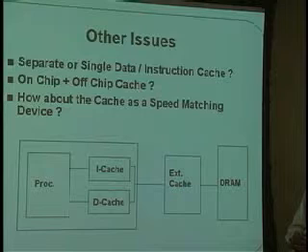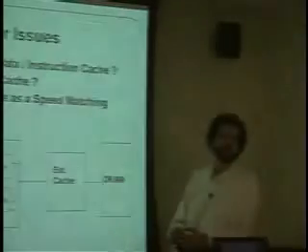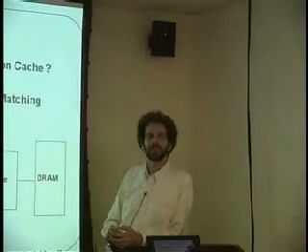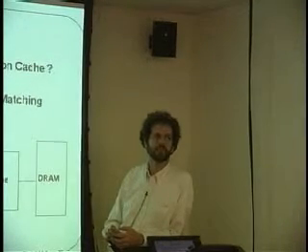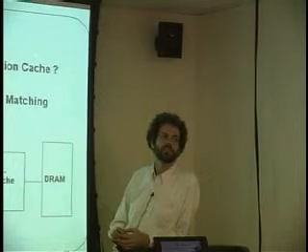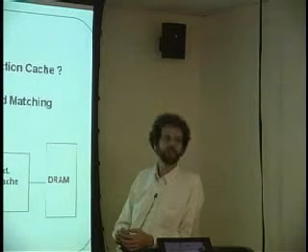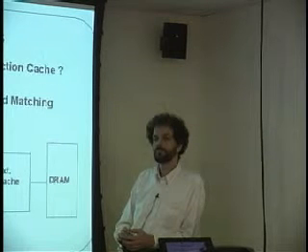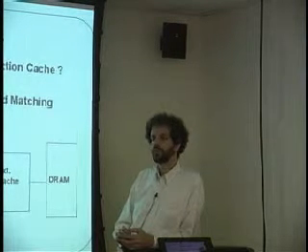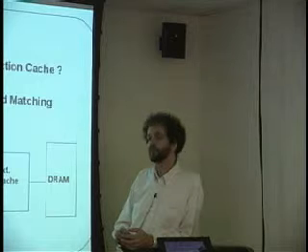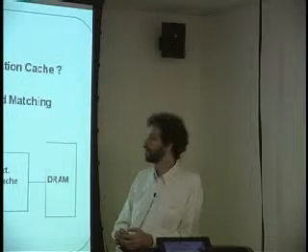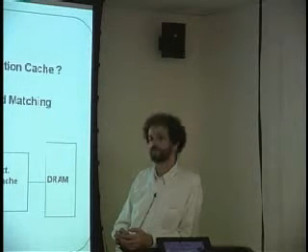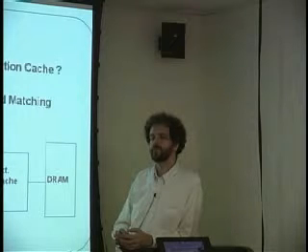And the reason is, again, the machine has a voracious appetite. And it's executing opcodes like crazy, okay? What it's not doing is executing loads and stores on every opcode. And so you typically see that the data cache is smaller than the I cache. Okay. Would these be of the same design? It's typically the same design. Sometimes the number of ways can be different in one versus the other. But that's a very, very difficult issue.